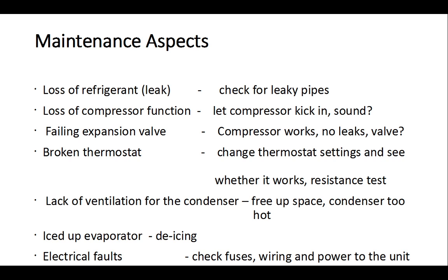Lack of ventilation for the condenser is a big problem as well. If you find that the condenser is dusted up and air can't go around freely, the performance and the efficiency of the fridge goes down. Also interesting, the more ice builds up on the evaporator, that's the bit inside the fridge, the more energy is necessary as well. And it can be that the condenser overheats because there's too much ice on the elements inside the refrigeration unit. So all you have to do is de-ice the evaporator: turn it off, get the ice off, and then turn it back on again, and that's all you need to do in that instance.